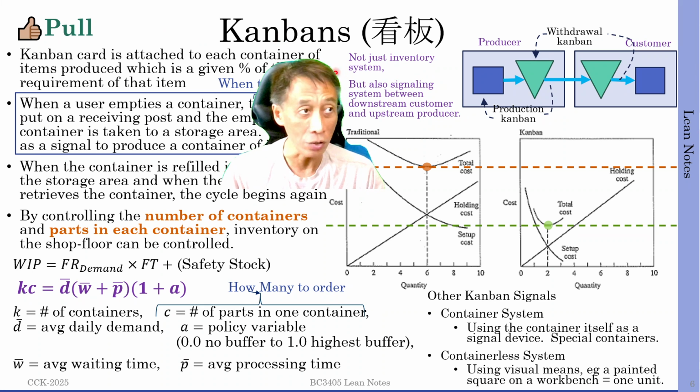The entire production line will be based on Kanban, so that when the producer needs to produce more, it will empty out its own raw material Kanban and swap with further upstream, and be able to, with the penalty of a little bit of setup time, be constantly filled with its own raw material input flow units. And that propagates further upstream, further upstream, up until the initial purchase of raw material.